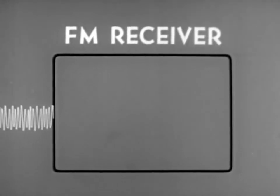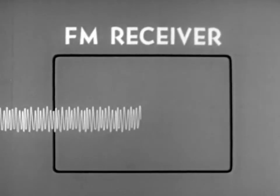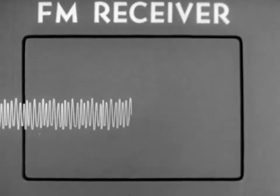The components of the FM receiver are a bit more complex, for they have an additional factor to contend with. The incoming carrier contains intelligence in the form of frequency variations. But it also contains amplitude distortions, hash, and static. These we do not want. Since these distortions are located along the amplitude peaks of the carrier, we can eliminate them by eliminating the peaks.